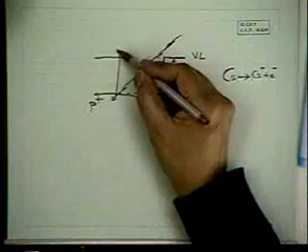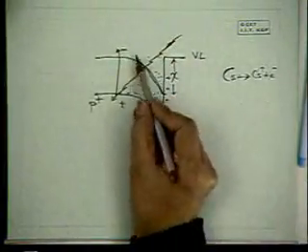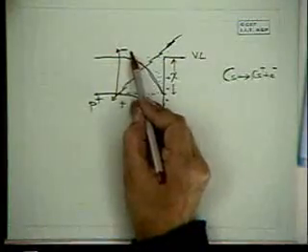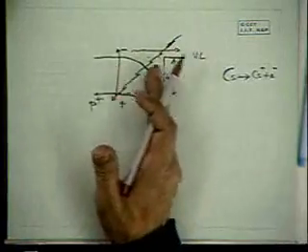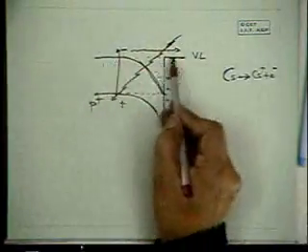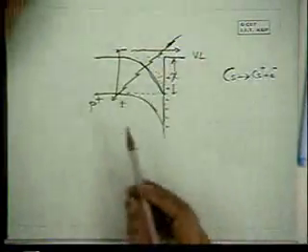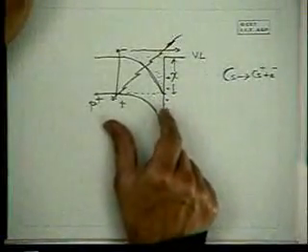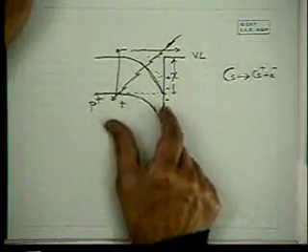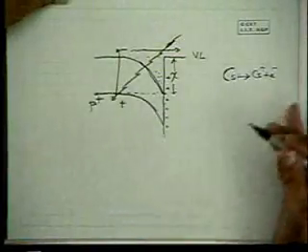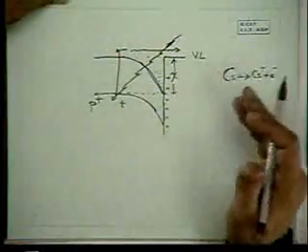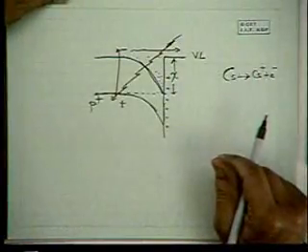you can have electron-hole pair creation, and the electron does not have any barrier to overcome. It can diffuse from a distance of almost a micron, the diffusion length. It can just diffuse into vacuum, and hence not only is the efficiency increased, but the range of electrons from the depth of the semiconductor from which the electrons are emitted is also increased, and hence one gets high efficiency, and the threshold of energy is also reduced.